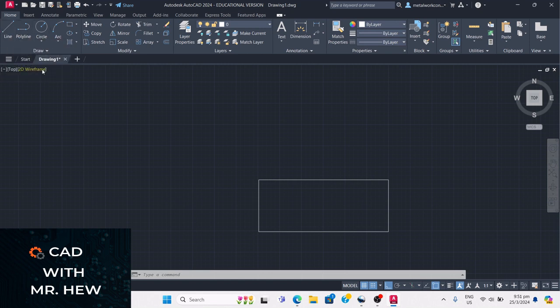The next command that I'm going to introduce you to is the circle command. So here's a circle. Now if you read the command line down here, it is asking for the center point of the center for the circle. Now look now. I'm going to hover over here and see that triangle. As there it says midpoint, the object snap is finding the center of the line for me. Okay. So if I move down here, see it says midpoint. If I move to the corner, it will pick up the perpendicular endpoint. All right. Good.